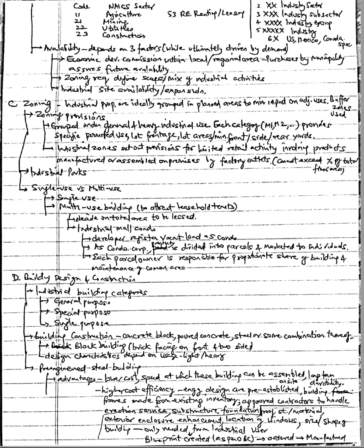To recap, most small and medium industrial general purpose buildings offer similar features and characteristics. For example, a freestanding structure typically includes both a main industrial area and an office area. The industrial area must have a single floor with a clear height, typically between 16 to 25 feet or higher, and requires a poured concrete slab on grade 6 inches or greater thickness depending on the need. Steel frame roof using open web joist, a built-up roof with stone ballast, steel strip windows, metal doors, and overhead doors for loading dock.